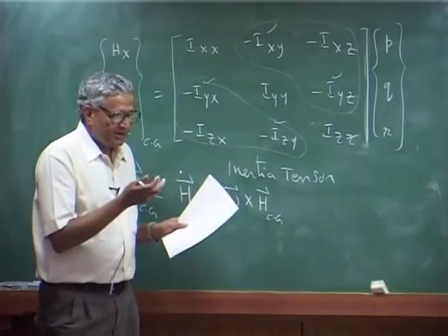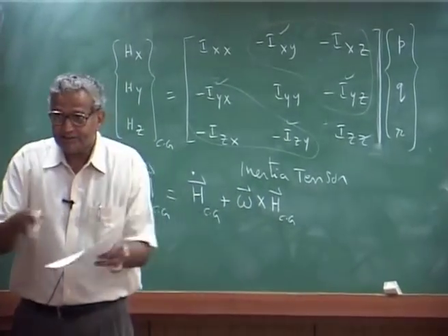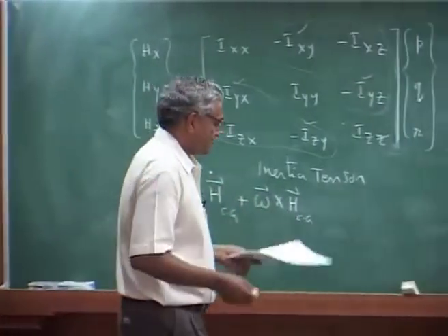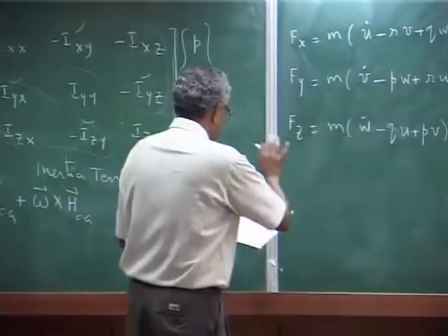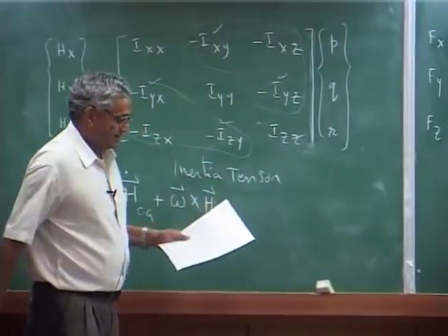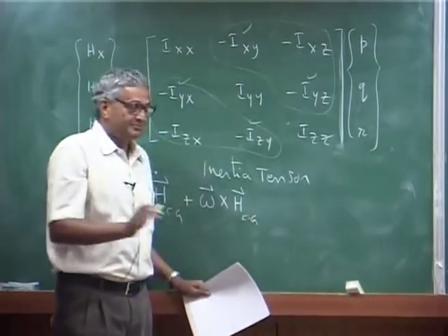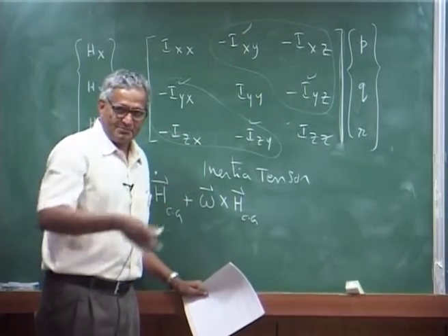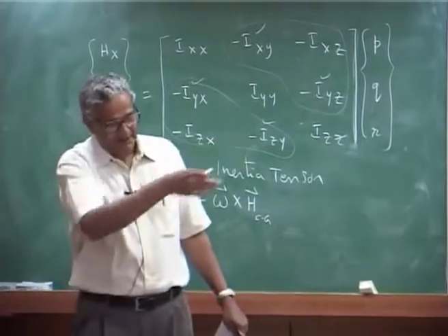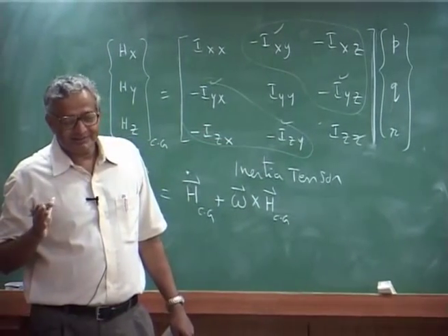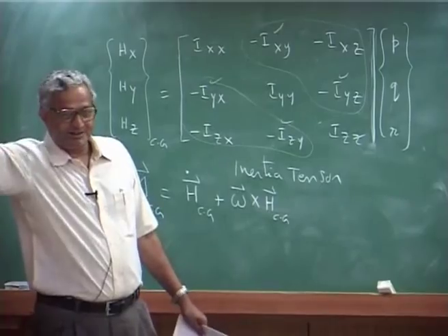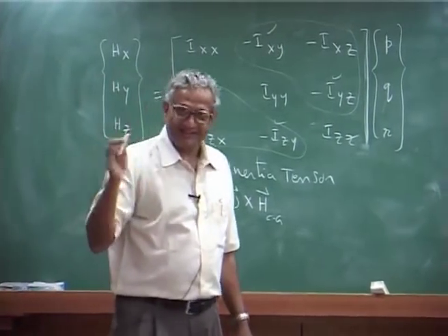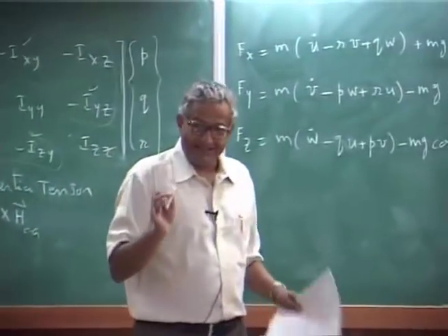If you have a computational aspect, you can carry it, it is not a problem. But for ease of understanding, they try to throw away a lot of things and then try to get a simplified version. Now, I will write generally all cross products except Ixz, that means these are neglected, okay. That is because in the aircraft case, yes, there is a symmetry, but in the helicopter it is not exactly symmetric, because your tail rotor is sticking out on one side.